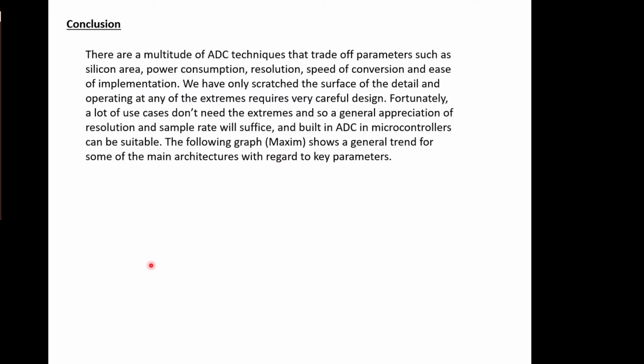So that was a quick run through of A to D converters. There are lots of trade-offs: area of silicon, if you're into that kind of design, the power consumption, resolution, speed of conversion, and ease of implementation.